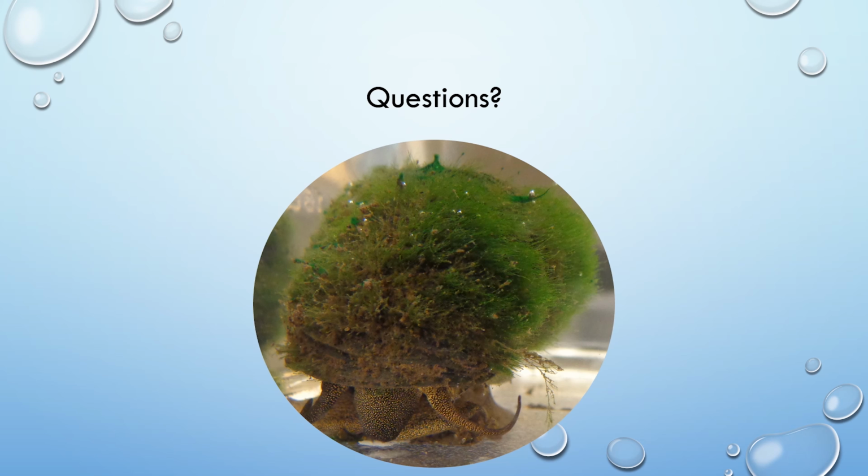I would really recommend in a situation with different ponds flowing one into the other that you really find out where the sludge is accumulating and then just target it in those areas rather than treating, say, the entire volume of the pond.